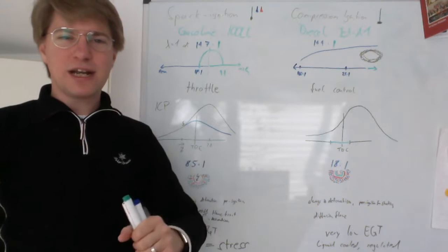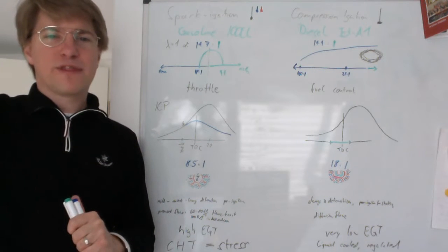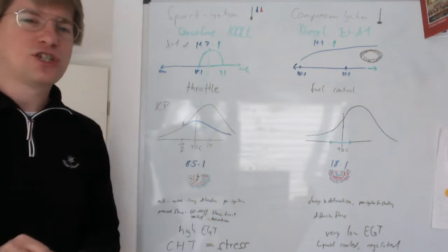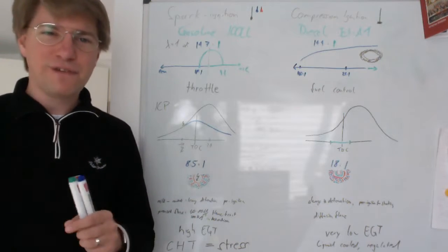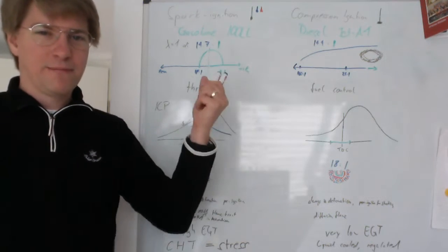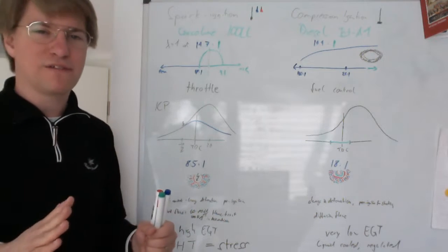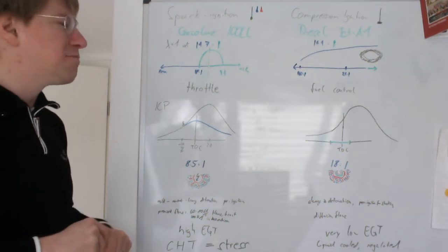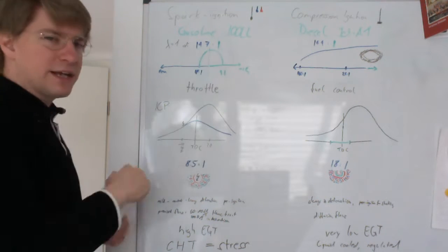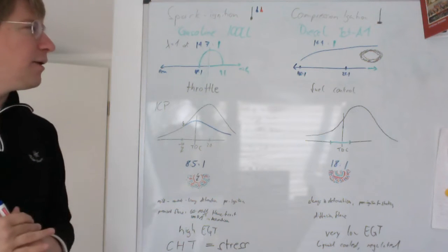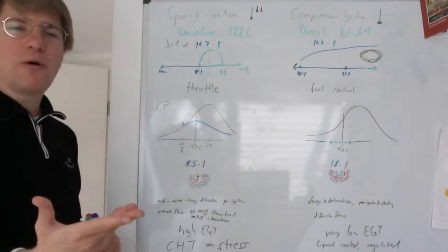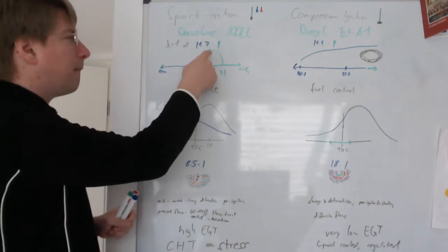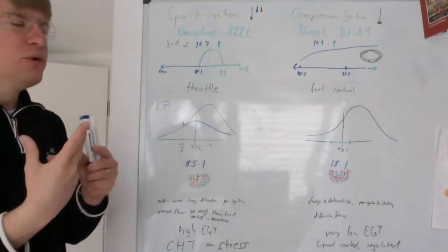So lambda is the ratio of air and fuel, with 1.0 meaning the optimal, or what the chemists call the stoichiometric ratio. At this ratio, every molecule of fuel meets a molecule of oxygen. The reaction happens, and we are left with no leftover oxygen and no leftover fuel if the combustion was really perfect. So looking at this curve here, this is the power output, the amount of energy that we get from burning this fuel-air mixture.